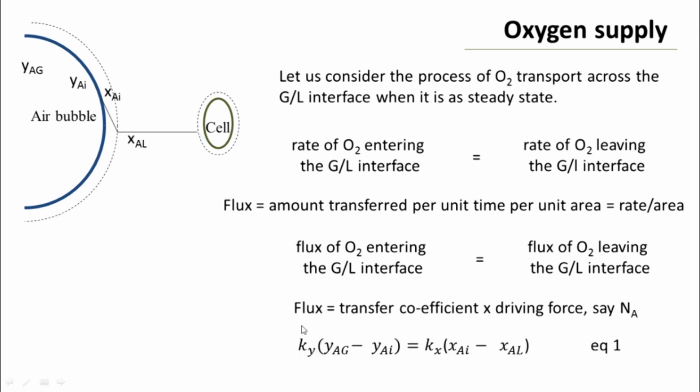The transfer coefficient is Ky, it is the mass transfer coefficient of oxygen. The transfer coefficient in the gas phase is Ky into the concentration difference, that is the driving force here. That is the transfer coefficient formulation, where the flux is given as a product of the transfer coefficient and the driving force. So the transfer coefficient Ky is here, and the driving force is the difference in concentration or the difference in mole fractions here, YAG minus YAI.